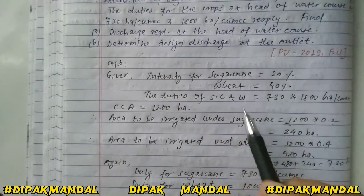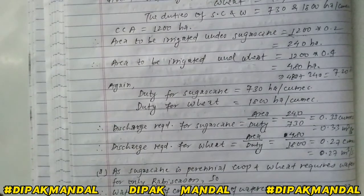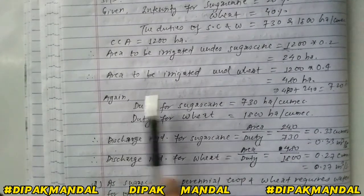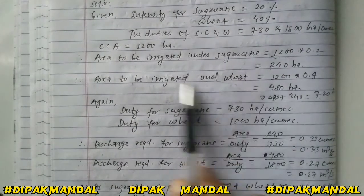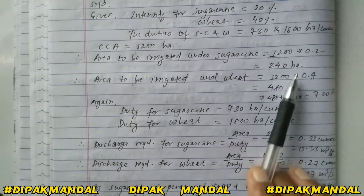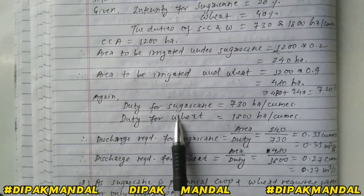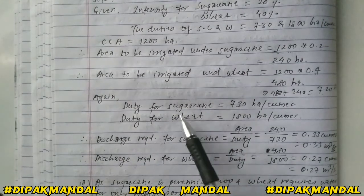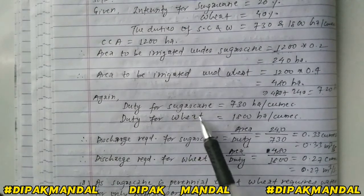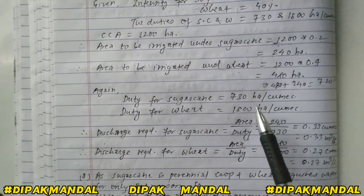As I said in the question, we can simply calculate this value. So let's summarize. First, we have to calculate the area: you can calculate the area with the given intensity, so we multiply these two values. After calculating the area, we have to calculate the duty for the different crops, that is sugarcane and wheat. In this question the value of duty is already given.